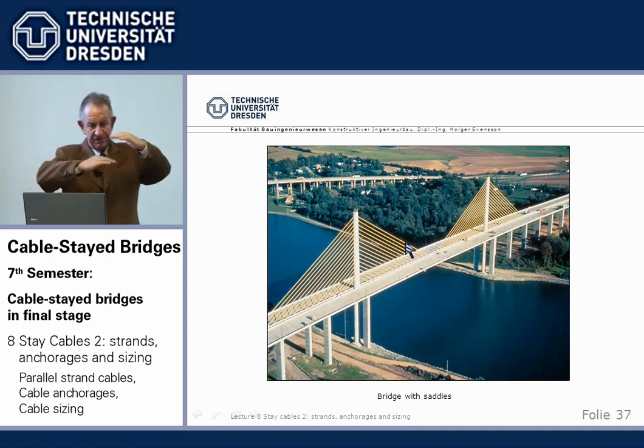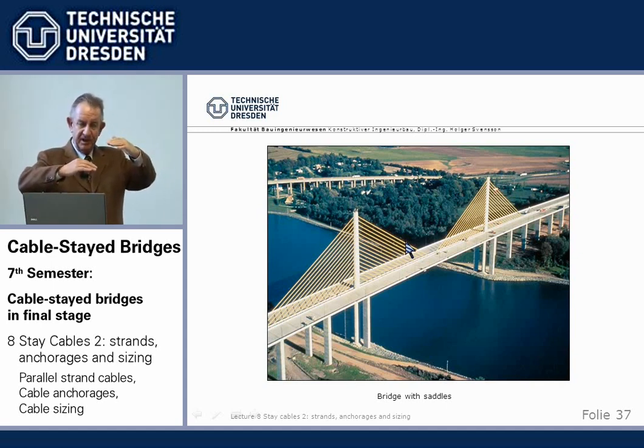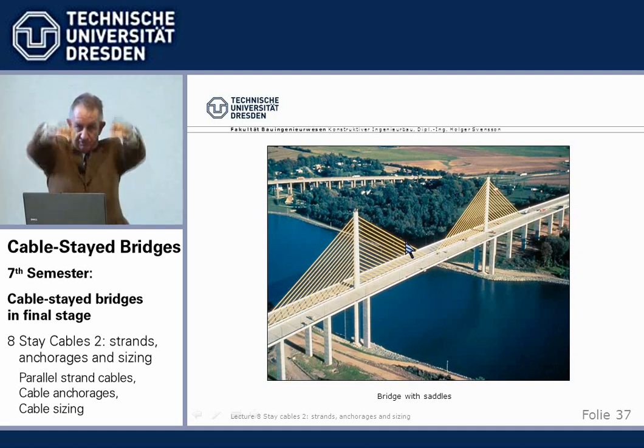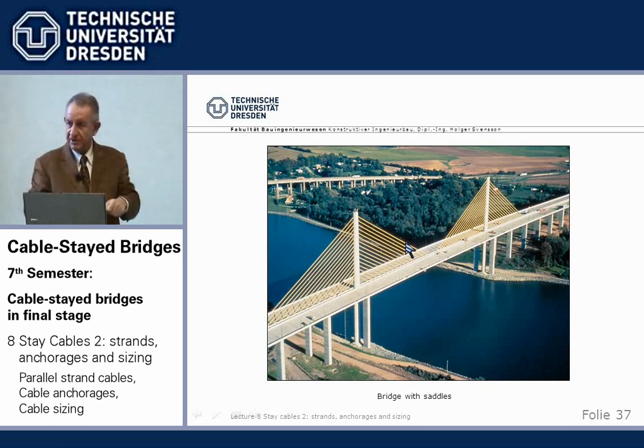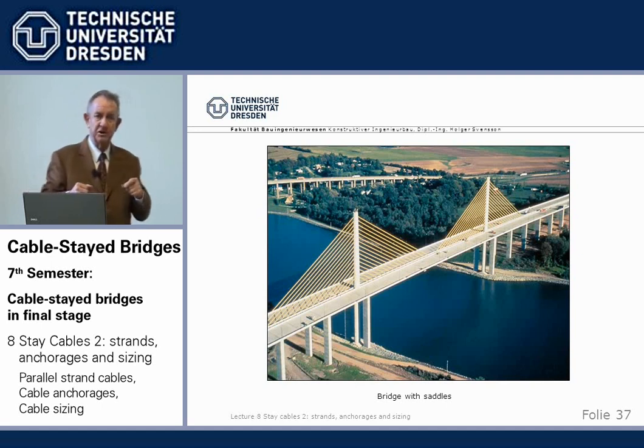What is normally the traditional method from suspension bridges is that we use curved plates with grooves into which the wire, the cable is placed into a groove on top, little distance, and then we have bolts, and we clamp it together. And then by friction, we can have a live load force in here, and no live load in here, and the difference is taken by friction. Okay, so far so good.